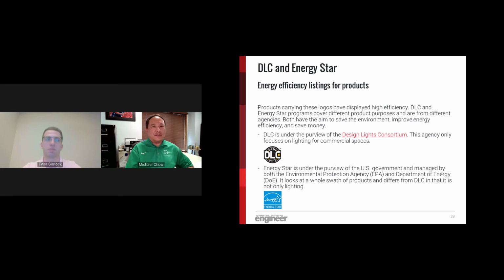And the reason to use DLC luminaires is the fact that they go through some rigorous testing. They actually pull luminaires off of the line and test them, make sure that they meet all the specifications as far as color and the color temperature, CRI, which is color rendering index, and the efficacy, the lumens per watt.